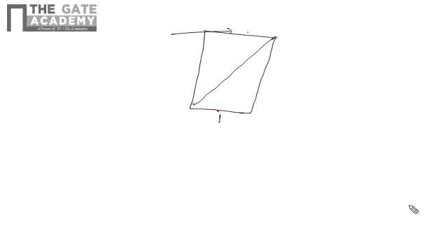Now if we want to measure the angle of shear, or what angle it subtends, we draw lines of 1 unit each from the sides, equal to the sides of this parallelogram on which the shear force is being applied. Then connect them with the edges of the parallelogram. This is the angle of shear, the theta we have defined. So theta is the angle of shear.